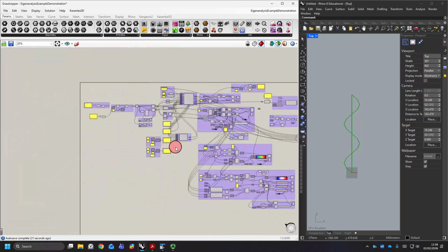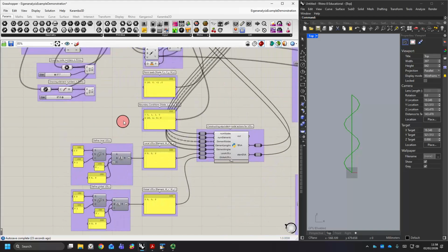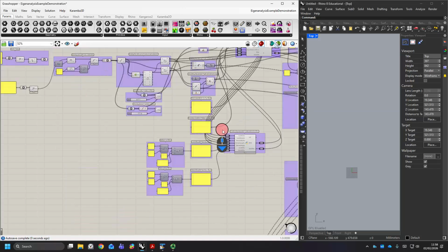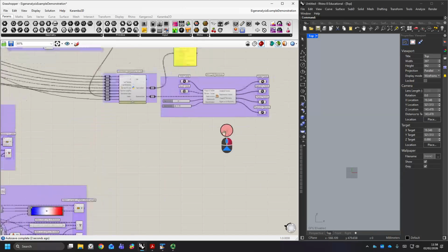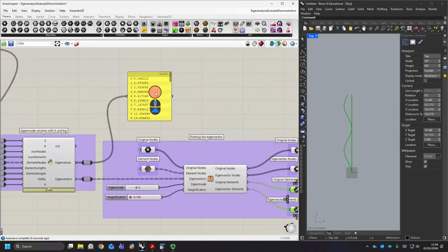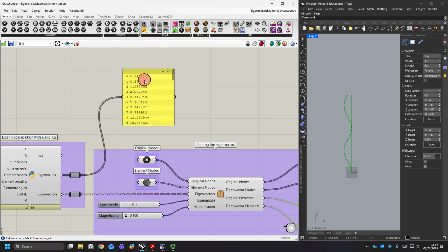What we can do is just to show again that everything's working. I'm going to alter the boundary conditions, so we'll actually just make it free completely at the top, but we'll turn it into a fixed condition at the bottom. And now if we zoom back over here, we can see that first mode is as we would expect, second mode, and so on and so on, and also our eigenvalues have altered here, so we can see the first mode is very low.